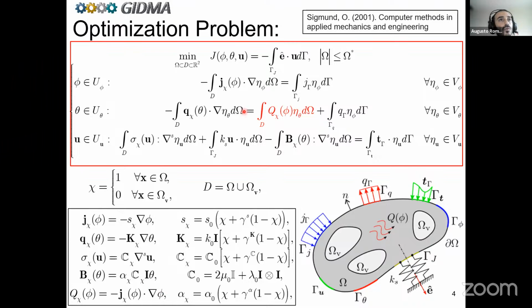And it is not necessary to solve it iteratively, because the method solves sequentially: first you solve this equation for the electrical potential field, then you introduce it, calculate this term, and then you have a linear problem. And then you move on and solve the next equation. It is a nonlinear problem because it doesn't match the linear properties of a problem, but it can be solved by a linear solver. Okay, thank you very much. I appreciate that.